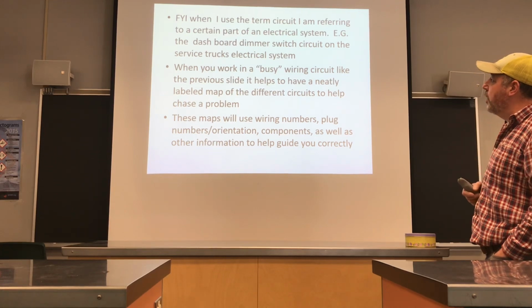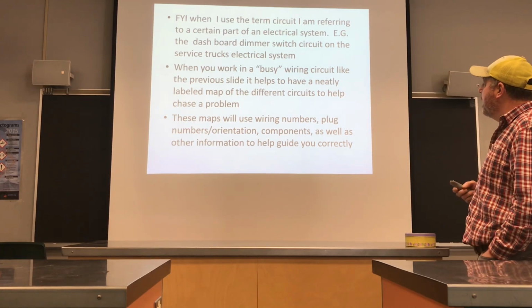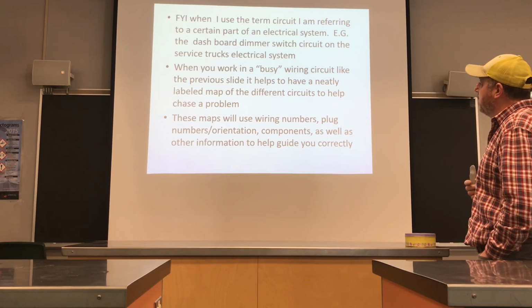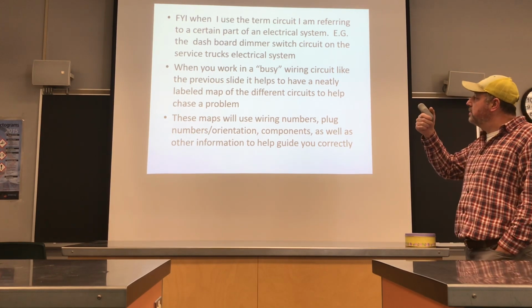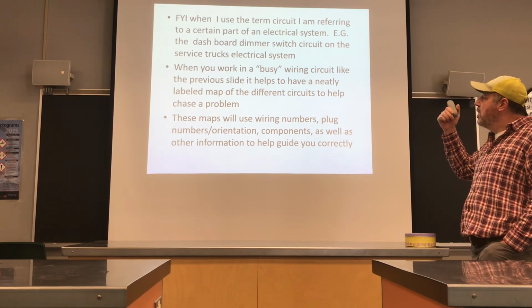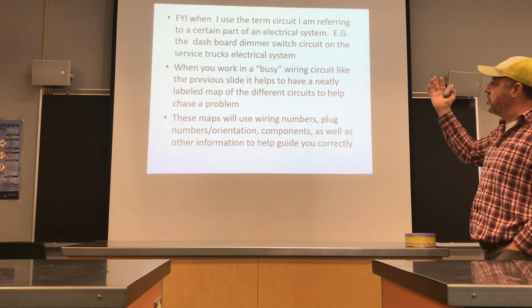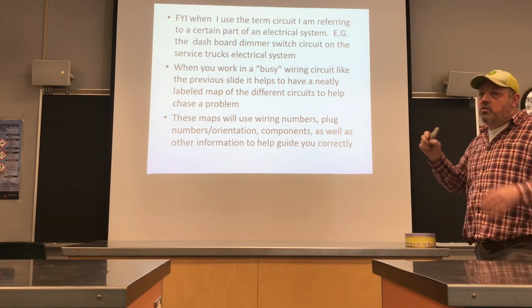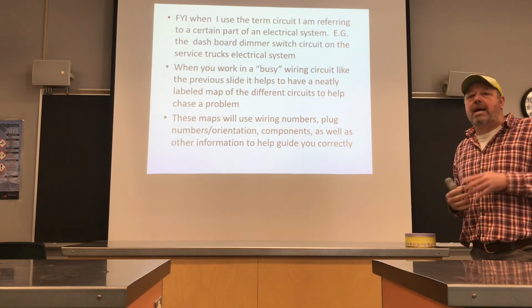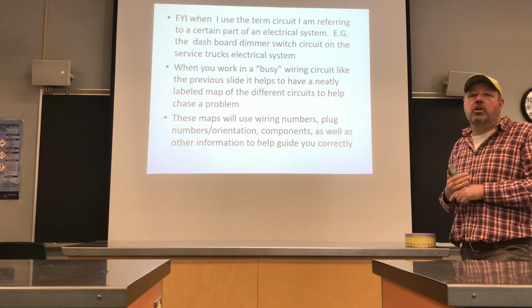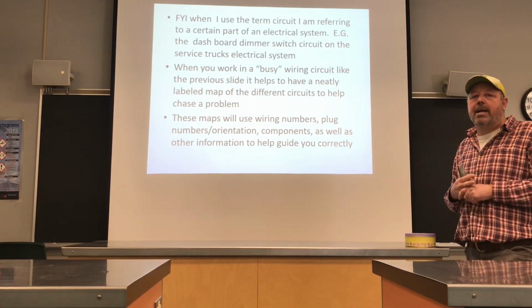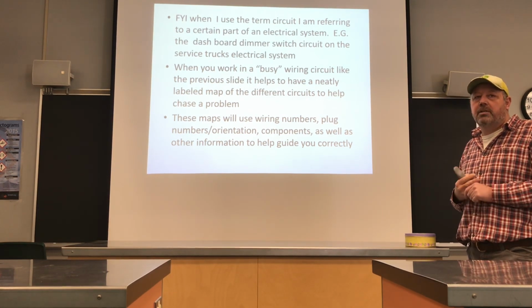FYI, when I use the term circuit, I'm referring to a certain part of the electrical system. For example, dashboard dimmer switch circuit on a service truck electrical system. So basically each component is going to have its own circuit. If we look at a horn, it'll have its own circuit within the schematic that makes the horn function.